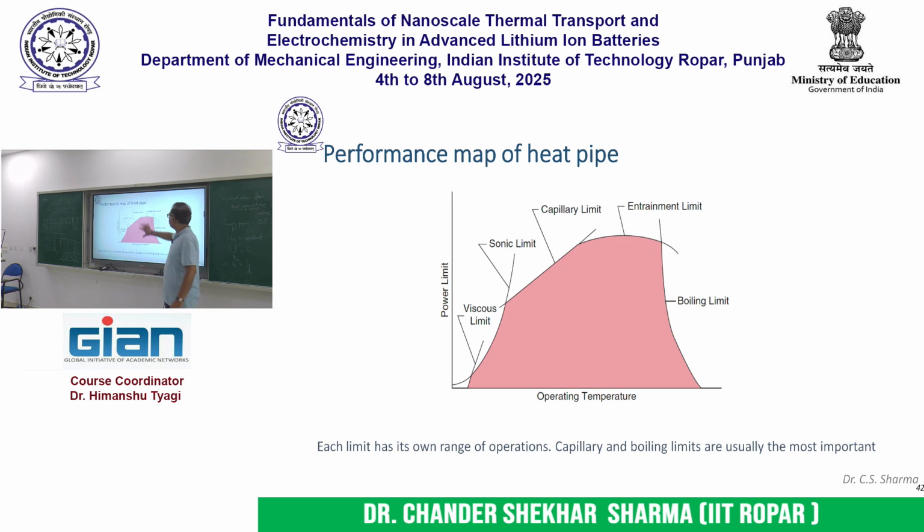heat pipe. Usually the capillary limit is the first to be reached, and so that is why it is the most commonly talked about, but in certain situations other limits can occur, and then the designer of the heat pipe has to be careful about at what operating temperature these limits will be reached, because any such limit will diminish the performance of the heat pipe.